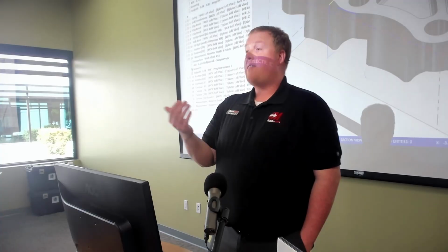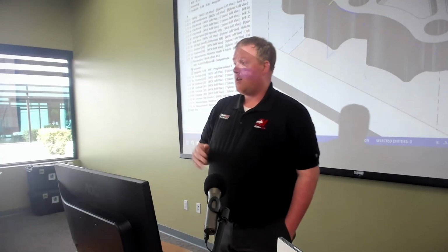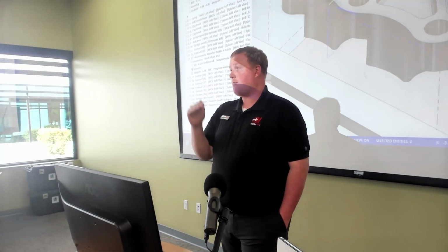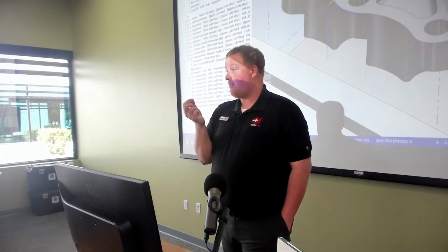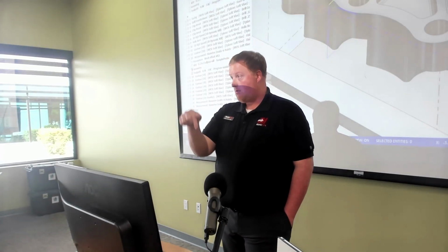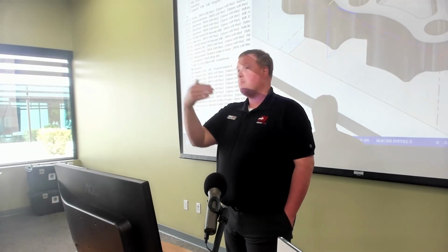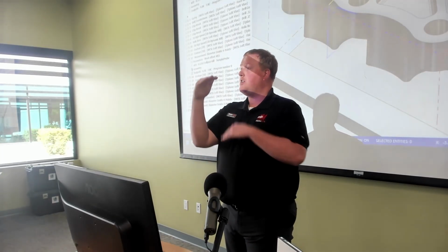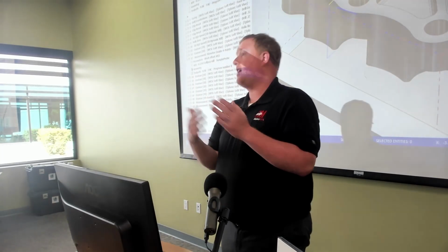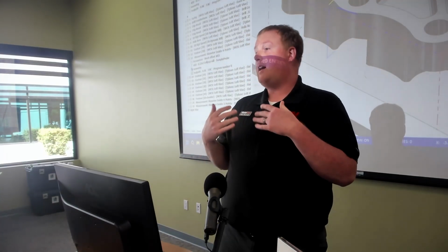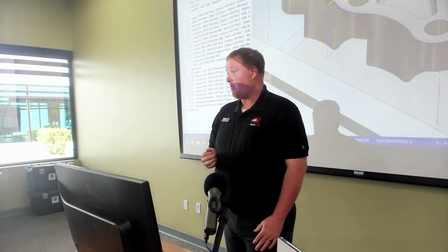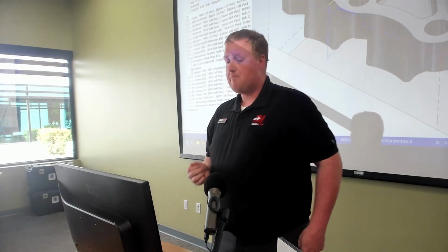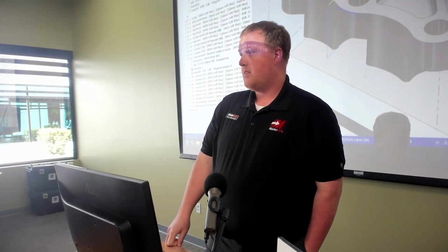That would have required me to take it out of the machine and put a height gauge on to find the differences. But with the probe, I was able to align to the middle of that thin edge, right? Probe in Z on the back side, probe in Z on the front side, do a feature to feature to find the difference in height and give me that data. So I know that, okay, it is within spec before ripping it out to properly check it and document as well. So, yep.